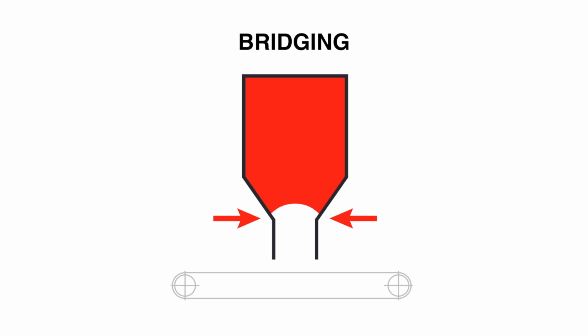First, the outlet itself needs to be greater than the bulk solid's bridging dimension. The bridging dimension is a minimum diameter for a circular opening and a minimum width and length for a rectangular discharge opening. If the discharge outlet is not bigger than the bridging dimension, then the storage bin will be susceptible to chronic bridging over the feeder. Essentially, good bin design is a game with gravity, and we need to make sure that gravity is sufficient to break the strength of the arch at the outlet.